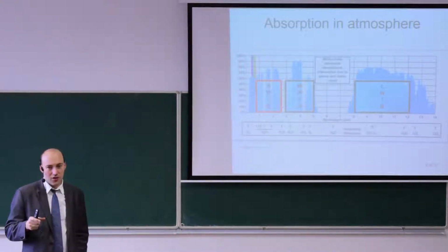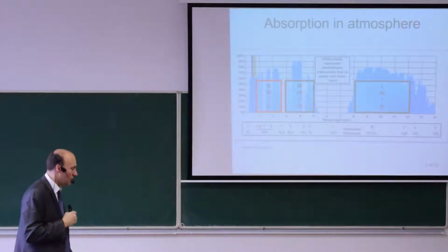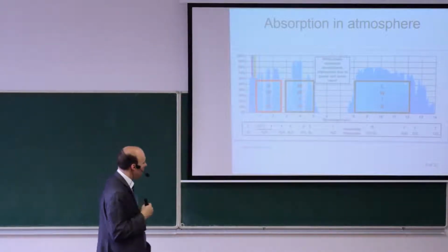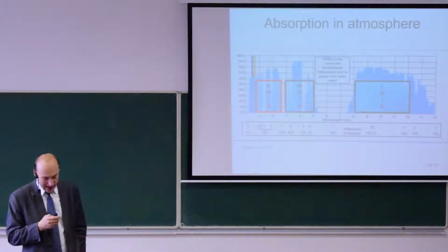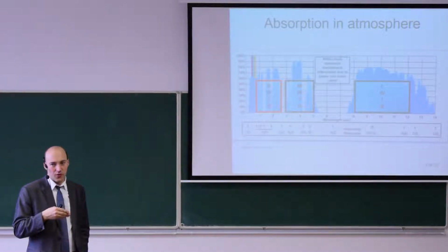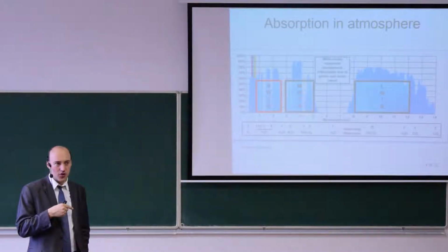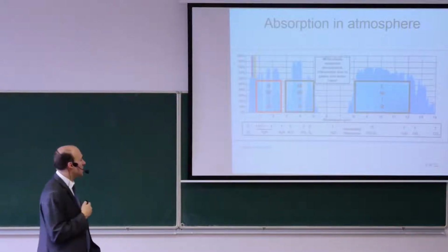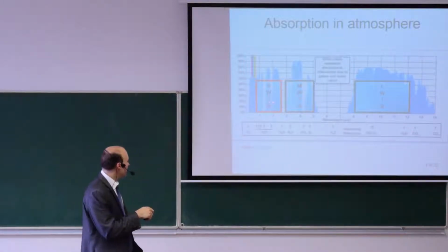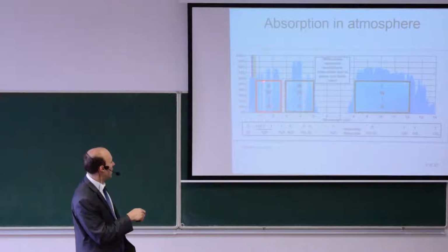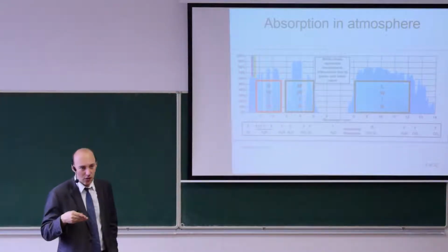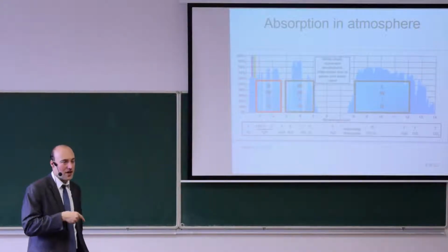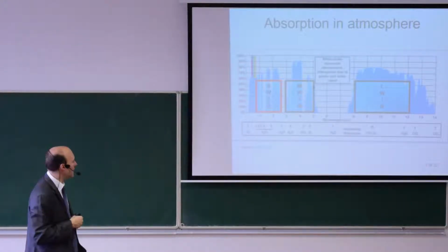Back to the absorption in the atmosphere. Whenever we want to measure through an atmosphere, we need to consider that there will be some absorption, and we can select a specific wavelength at which we know that the absorption is minimal. So you can measure in the shortwave infrared spectrum if the object temperature radiates enough at this wavelength.